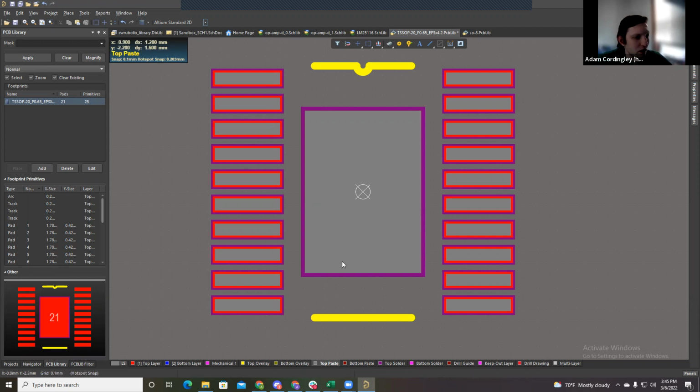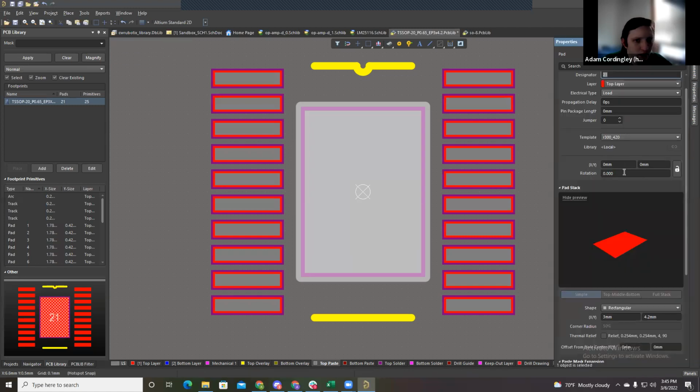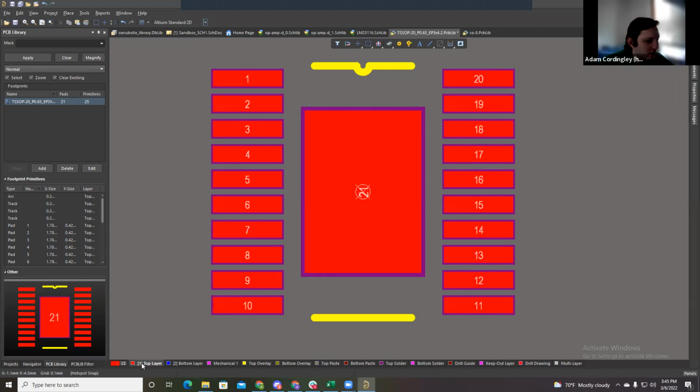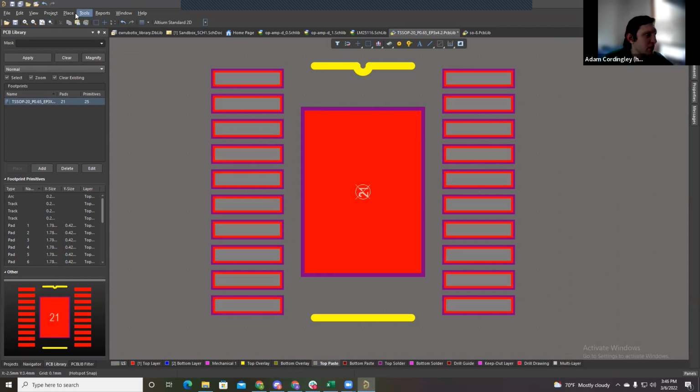We'd probably like little squares of paste with sort of spokes in here, so that the squeegee they use to spread it across, you know, is so flexible that if you didn't have spokes in the middle of this, it'll squish down into the paste, and it would scrape some away. And so I'll just show you what we're going to do. So let's go to our properties again. For our expansion, we're going to make it like -3, some large number. Now you can see there's no paste cutout. So we're going to add ones manually.